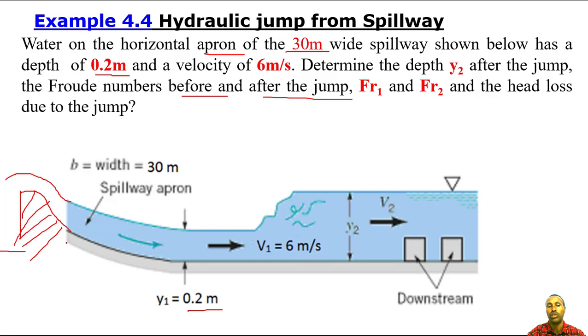Once you have the spillway, you have overtopping, which is like this. Then downstream of the spillway, you have depths at this point with a velocity of 6 meters per second. You may put some chute blocks, staggered. You can put baffle blocks, and sometimes you have an apron. Then, to dissipate the energy, the flow must be going slowly, to avoid erosion or scouring of the downstream river bed.